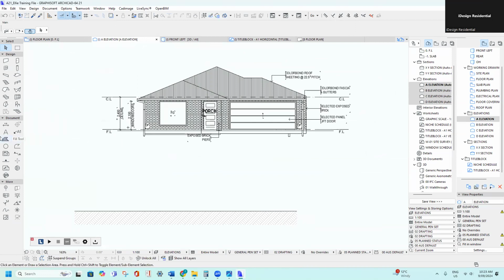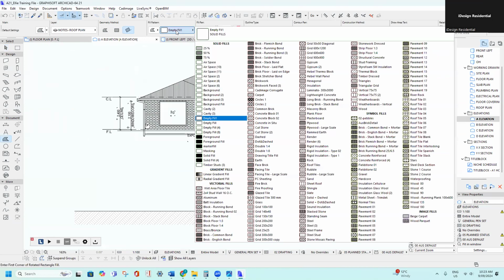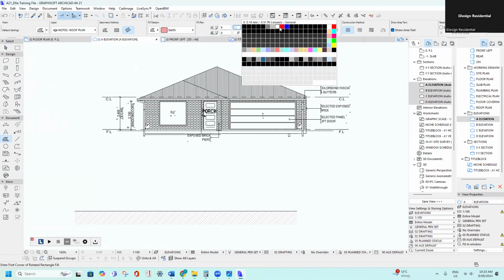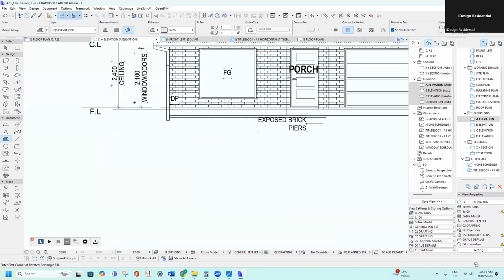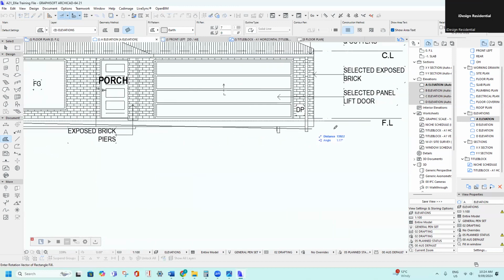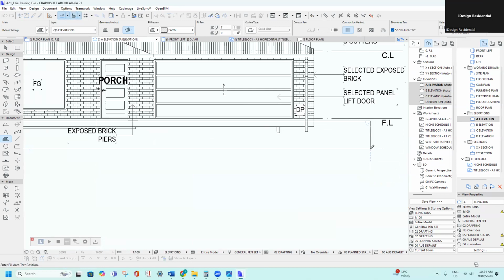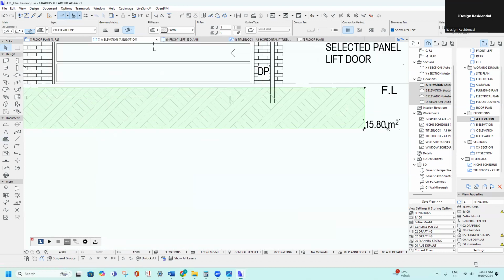And then I'd click on the fill. I go up here to the pattern. If you type in EA for earth, it'll bring the earth fill up, and then I'd make that gray, not red. So I'd put it on this number 7 and press E for elevation and click on elevation. And then I'd click here, make sure it's on this one here, rotate a rectangle, draw a straight line. I'd click there and then just drag it down and press 1000 and enter and press escape. As you can see, it's got an area there.